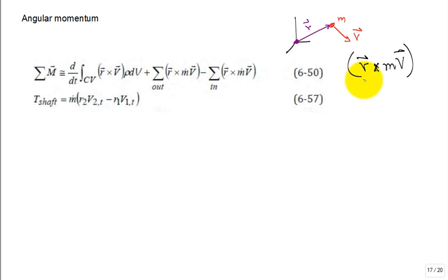So when you look at cross, this is just R cross M and the tangential component. You replace that cross product by just a multiplication. Mass or mass flow. That's a mass here. I'm just looking at a chunk of mass. I'm doing a little review of dynamics. Okay. And this V is the tangential component. So we would decompose into a tangential component, such that it's 90 degrees. True? Makes sense? Yes? No? Okay, well, that would be the angular momentum of that particle around there.